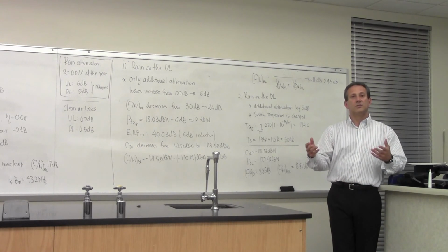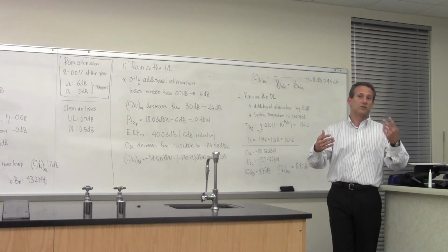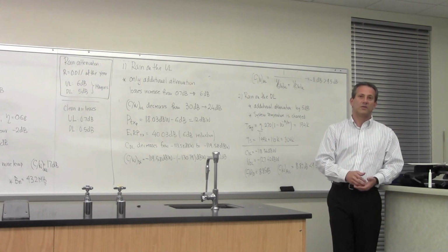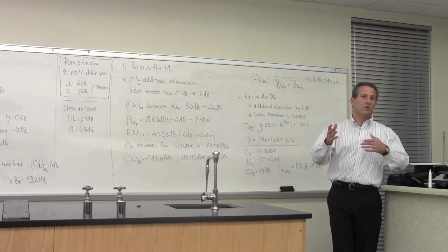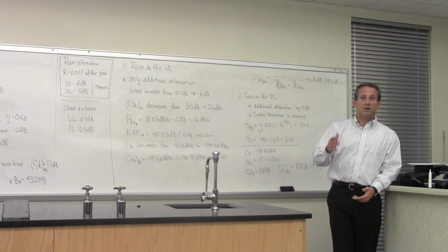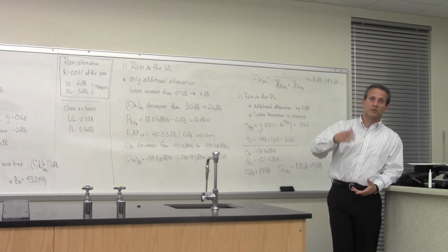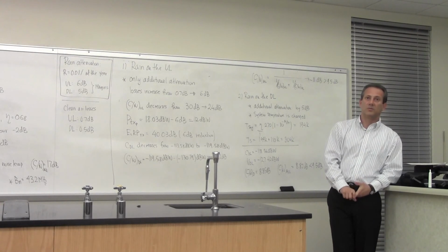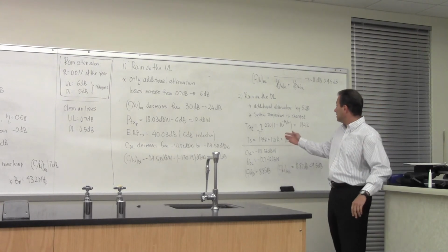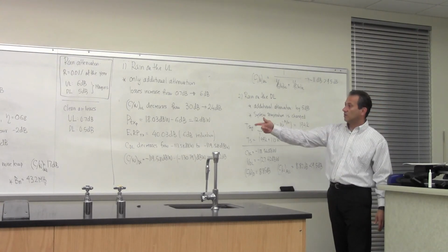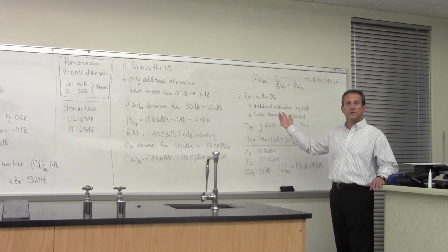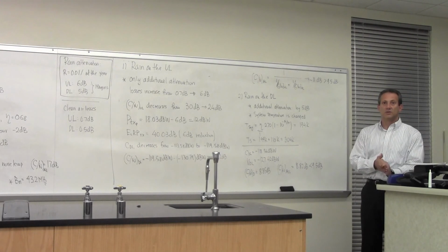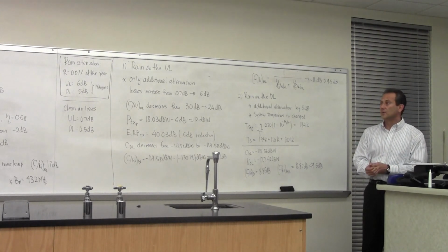The overall system temperature on the uplink consists of majorly two components: whatever comes through the antenna and the front end of your LNA. And both of them don't change. On a downlink, the situation is different because, in the absence of rain, you're looking at clear sky, right? So the temperature changes, and it can change by an order of magnitude, so the difference is significant. On the uplink, it changes by a fraction of a dB. So, thank you.